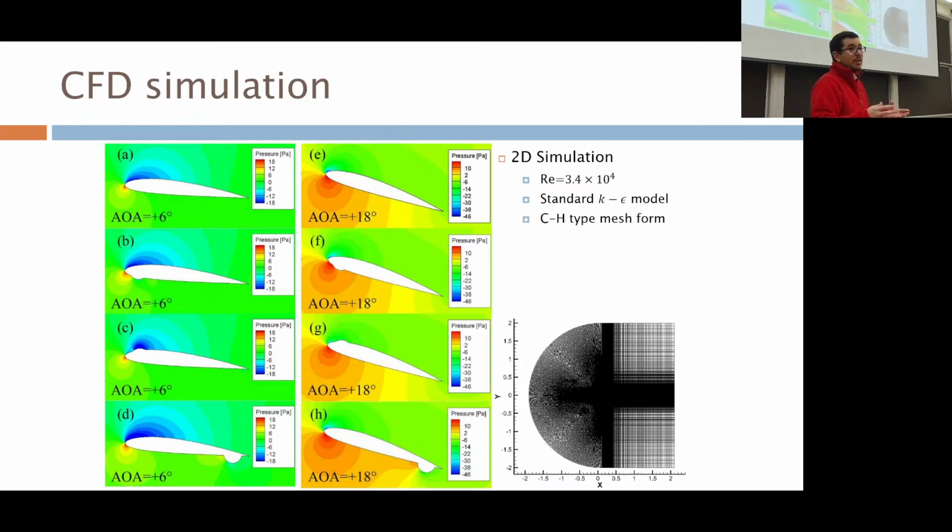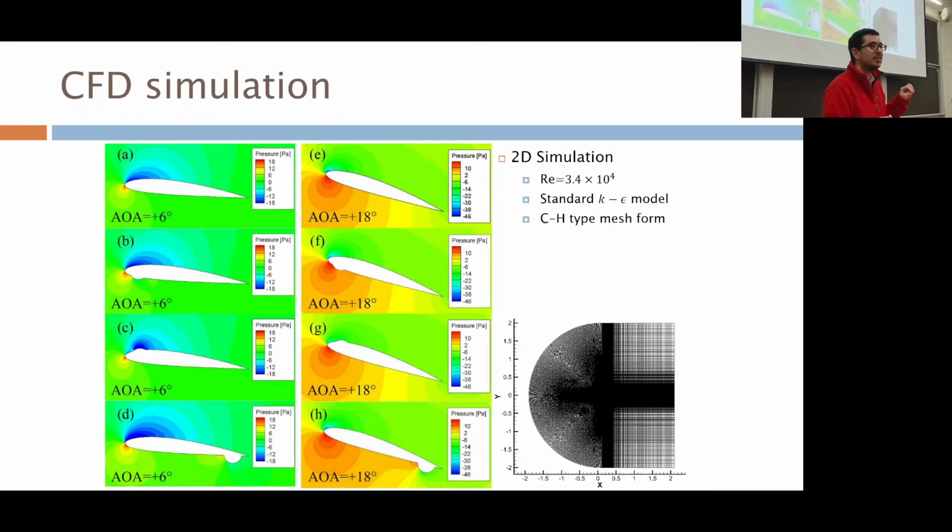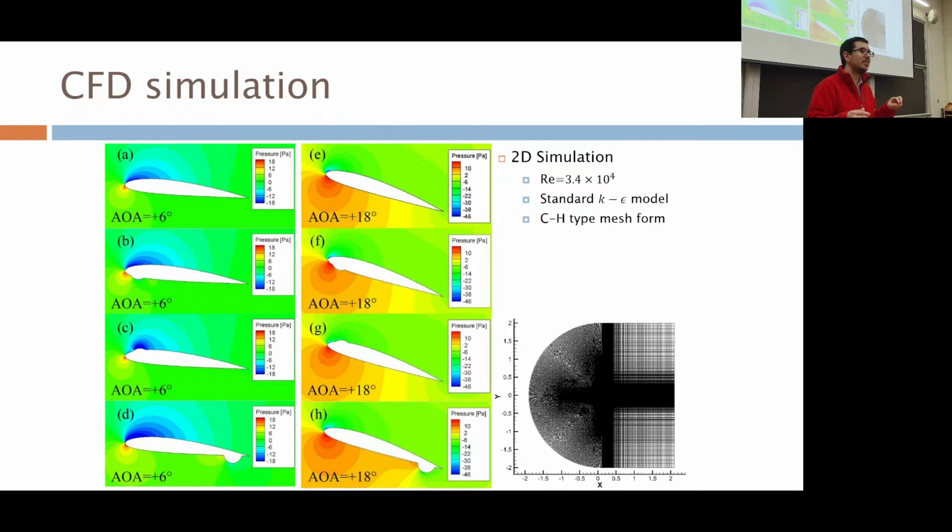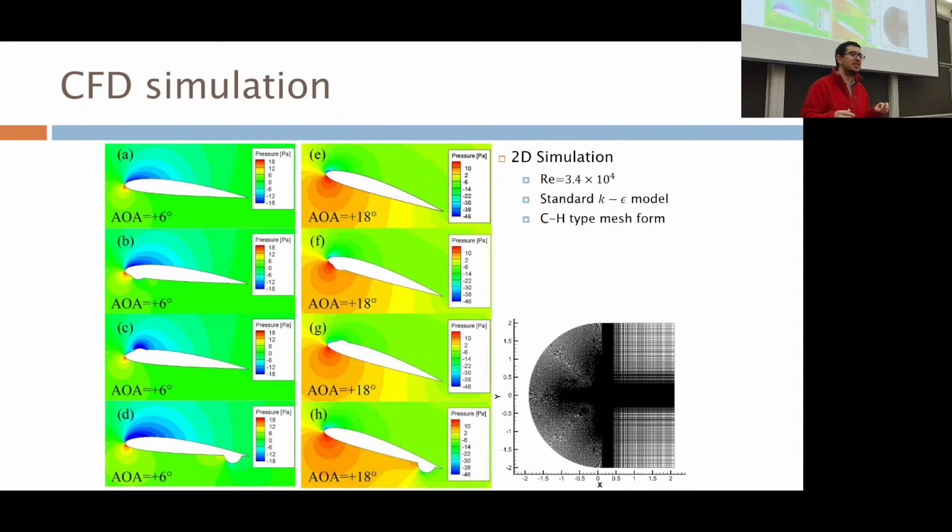Well, I didn't know this about airfoils. Anyone have any ideas? Yes, Arya? Depending on where you put it, you can kind of regulate how much that part of the wing will rise or fall. Because if you create a low pressure zone, it'll pick up the front of the wing more. Okay. Or if you create a high pressure zone underneath the wing, it'll also raise up the front. Good, right. So Bernoulli is in effect essentially here, okay?